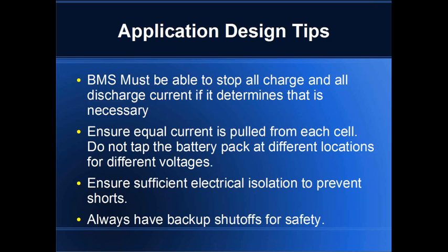Another thing is to make sure that there is sufficient electrical isolation everywhere in the battery pack to prevent shorts. Where that often becomes problematic is if you have something that's monitoring temperature.